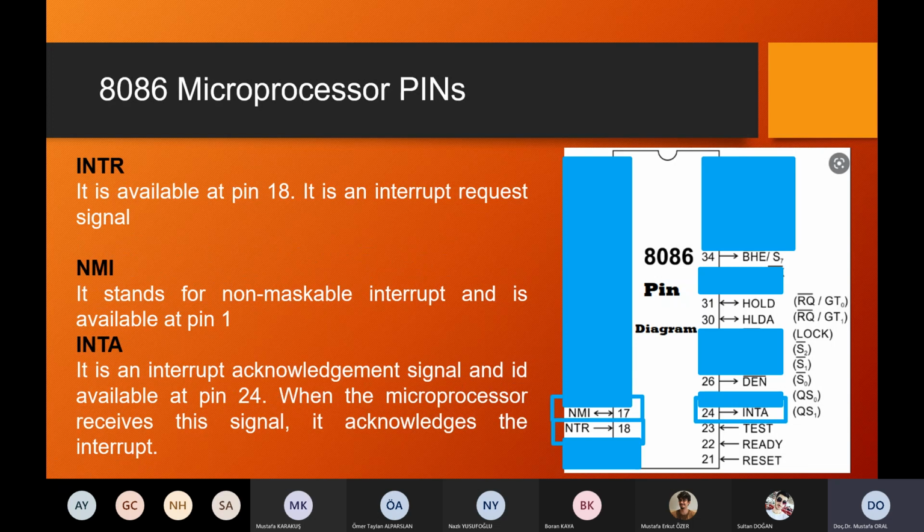Imagine that there is a process running smoothly and something urgent happens, or some conditions are met. In this case, the external device signals the 8086 through the interrupt, stating that something important has occurred, and to stop whatever you are doing and jump to or initiate the interrupt routine, which is a sub-program, completely different.